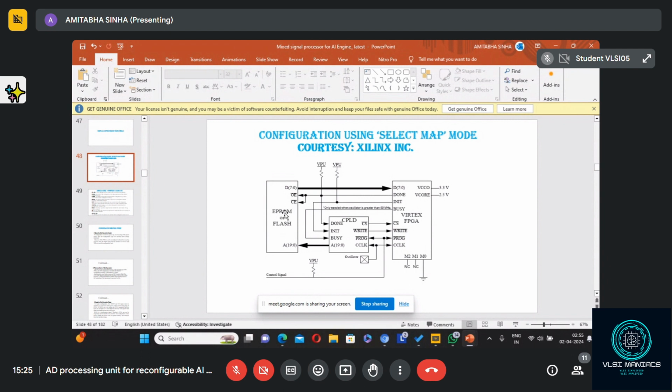Then what will the memory do? The contents of the memory at the address given by the CPLD will go to the FPGA, and that data will be downloaded. And again, this done signal will be low, then high.